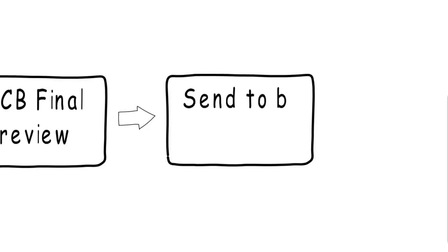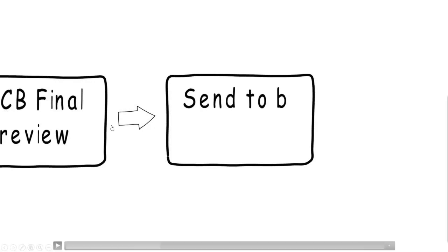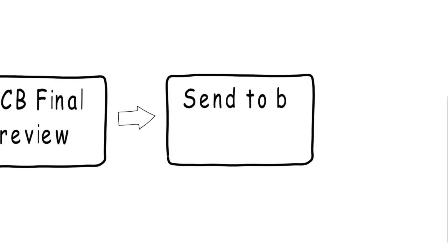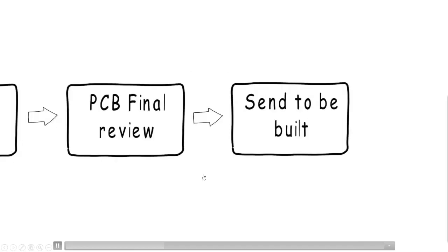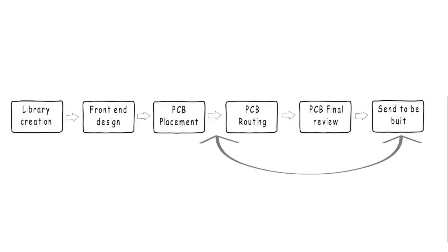Of course, through this process, you are doing basic design rule checking that we all put in the PCB to help prevent copper violations, or copper objects overlapping other copper objects, that would obviously make the design not work. But the one thing we don't do is go through the extent of, and no CAD tool really has the capability of doing it, doing true manufacturing and assembly verification.